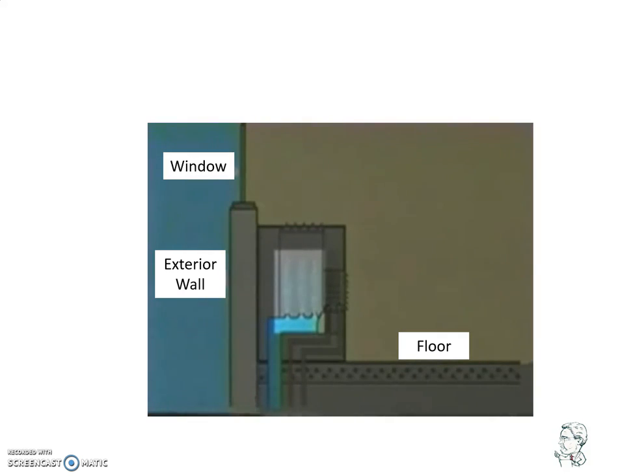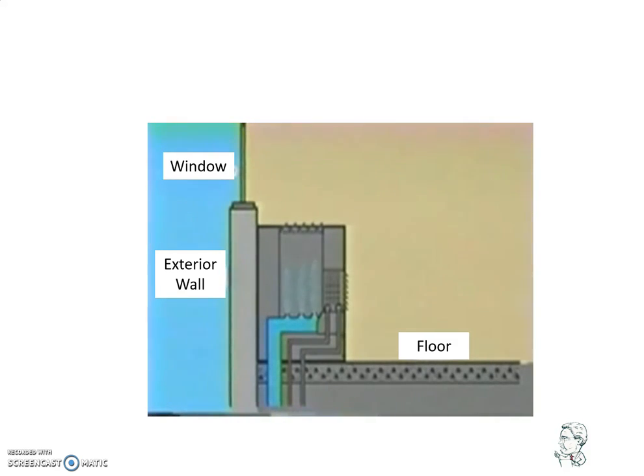In so doing, air already present in the room space is induced to flow into the unit and mix with the discharging new air. As the air is induced into the unit, it passes through a heating coil, either electric or hot water, which is controlled by a local thermostat.